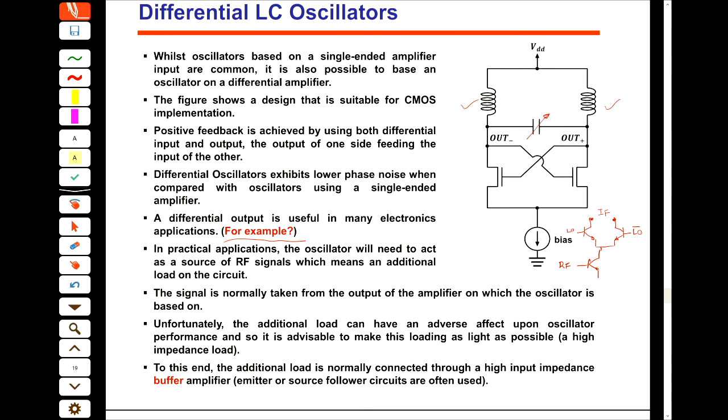All right, so it's mentioned that after this oscillator, when we get the output from these 2 points, we want to connect it to our load. But when we connect it to our load, it always has input capacitance, inductance or resistance, and then the frequency that we made is changing. So this is the problem that we usually get.